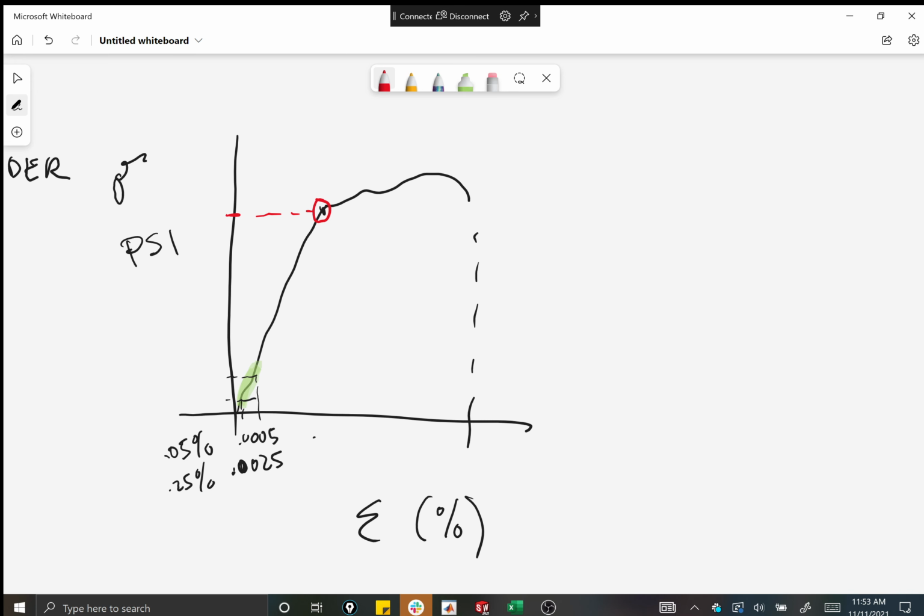But the reason I'm bringing this up, so in your modelers, when we get down to actually trying to put numbers to our trusses, we're going to have Euler and Johnson's, which are loads, right? We're saying at this length, this member is going to fail at this load if it's an Euler length. Then we're comparing it though to a pure compression value. That's load at yield. And why yield? Because